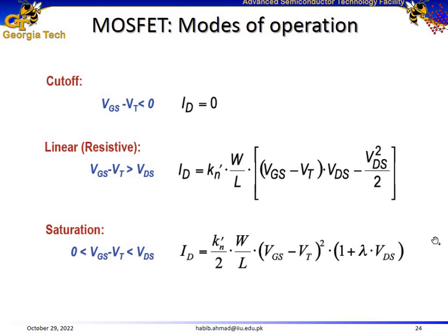Once again, these concepts are crucial for discussions that are going to happen in the coming lectures. But you got to remember that our ID, the drain current, is proportional to W divided by L, or especially to W, and that's why we play with the W parameter for the PMOS and NMOS transistors to balance the currents for these two kinds of transistors for the inverter.